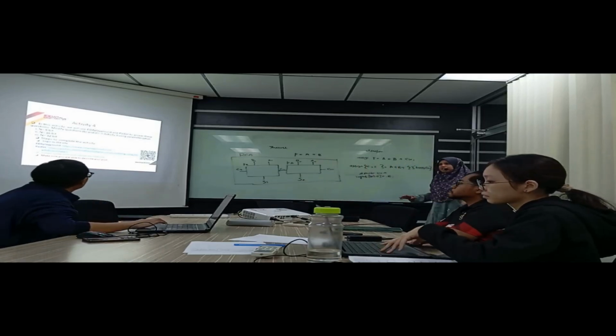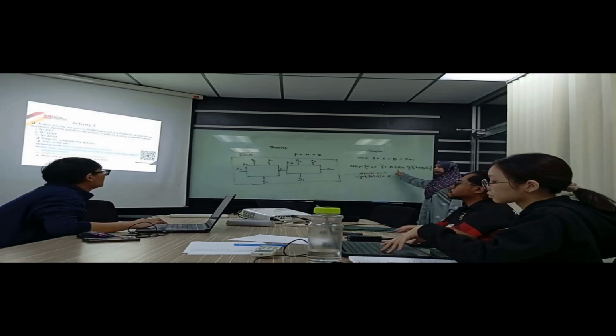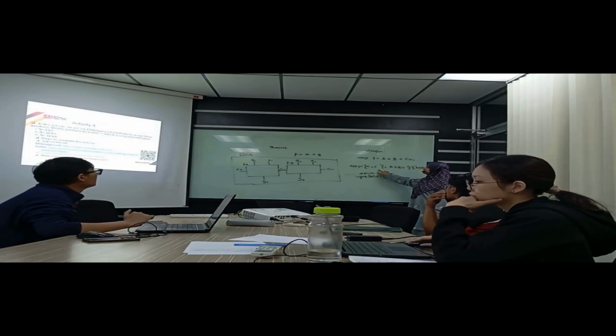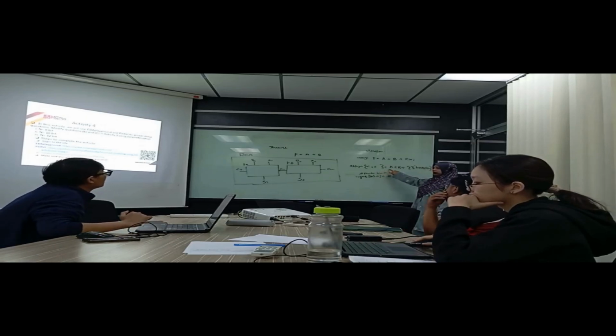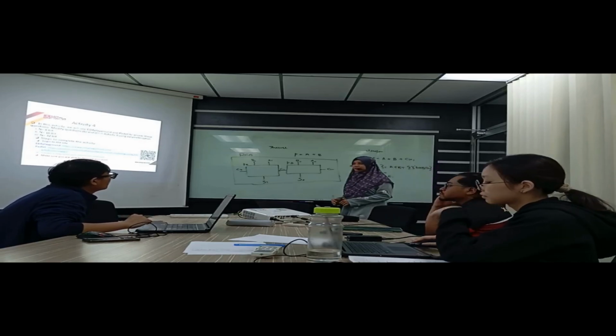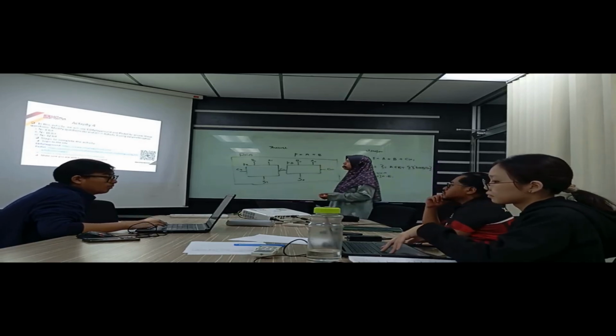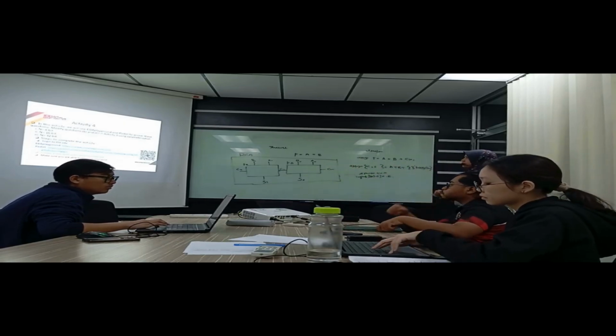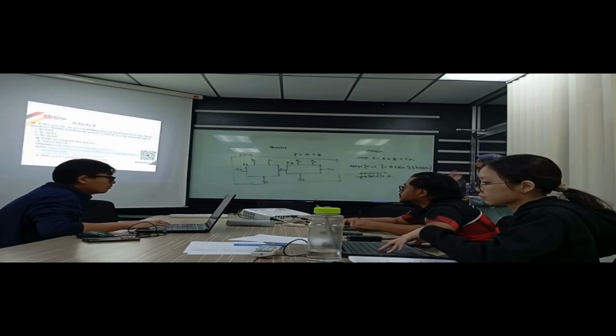I think the easy way is to use data flow modeling. Just use this line of code in data flow modeling. Let's say you used 4-bit previously, right? After that, you just call this module and change to N equal to 8, N equal to 16, N equal to 32. Try to do this and share here.